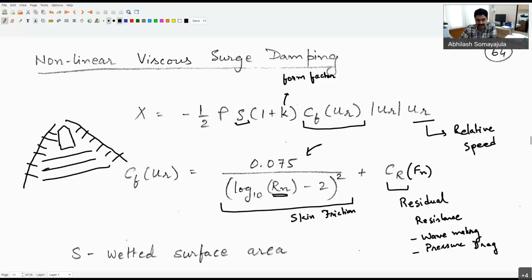And we talked about the idea that typically we always scale our models using Froude number. So whenever we are doing the scale down, the skin friction part will not be matched between your prototype and the model. So you have to figure out an extrapolation technique so that the skin friction part which we measure on the model can be extrapolated onto the actual prototype scale. Now there are approximations, they don't always exactly work the same way. So you may see some amount of difference, and these are what are called scale effects.